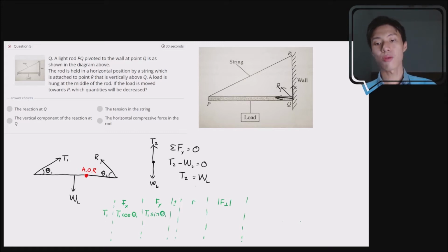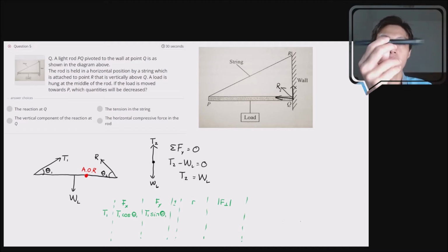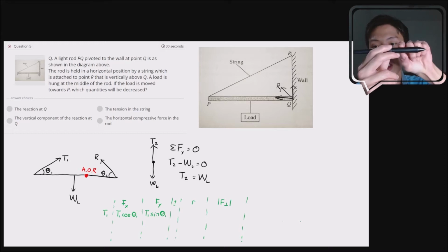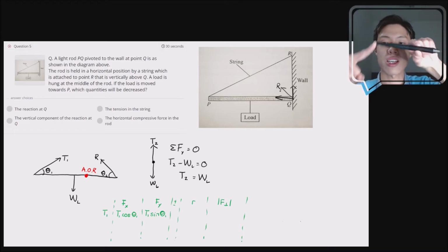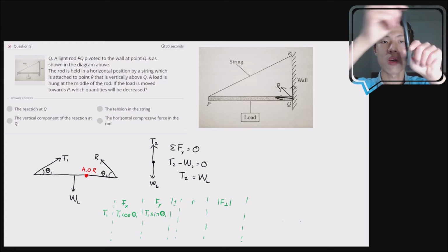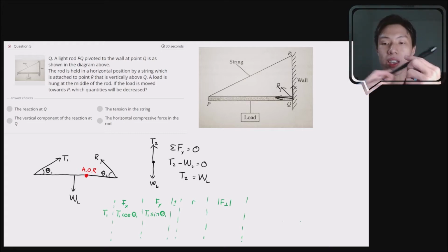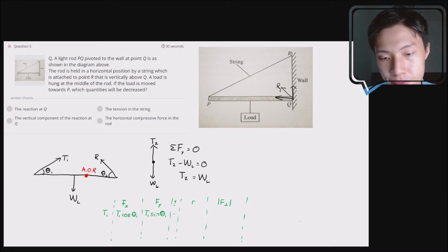Plus minus, whether it's a positive torque or a negative torque, we need to see whether this torque here is a clockwise torque or anti-clockwise torque. So hold our pen here to represent the light rod, pin ourselves at the axis of rotation, then try to push the same way as the tension looks like. So the tension is in this direction. So if we push in this direction, we see that the pen will rotate clockwise. The pen rotate clockwise means it's a negative torque.